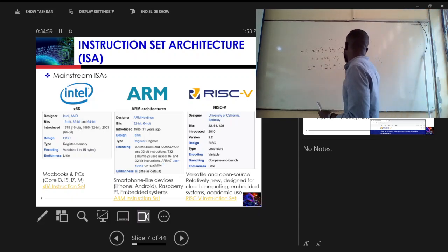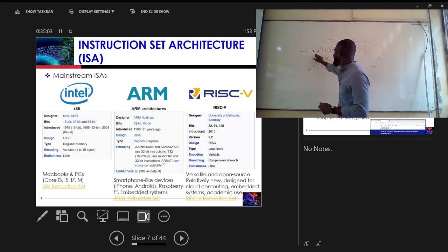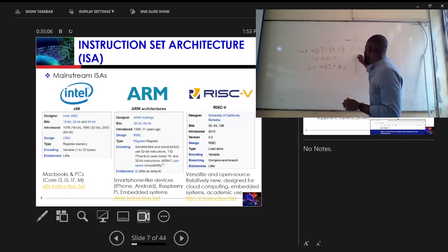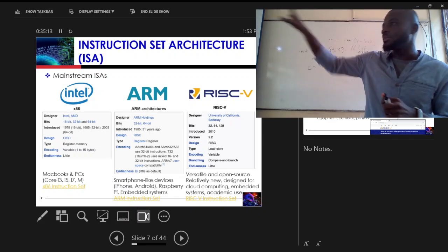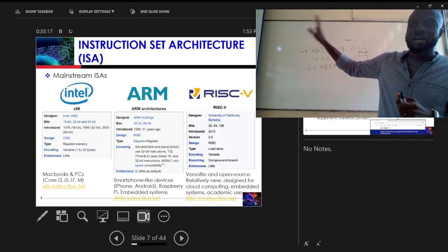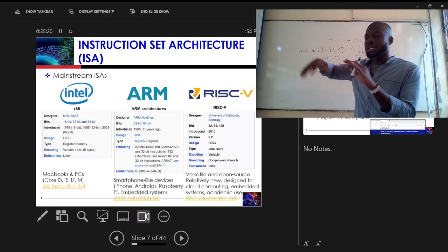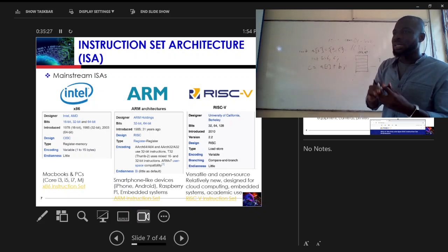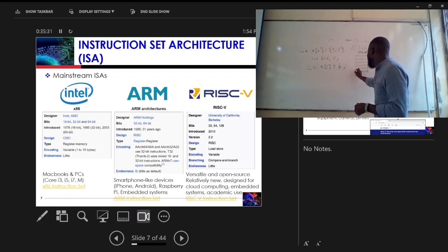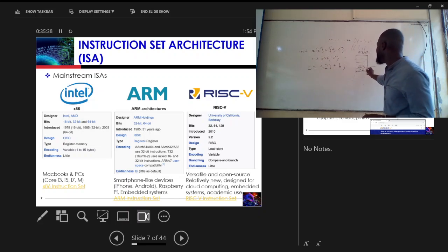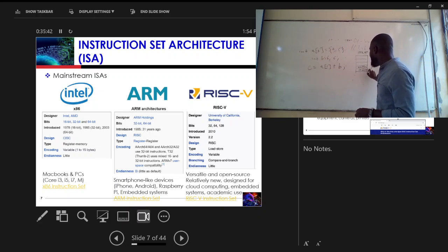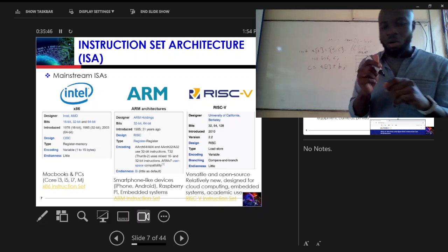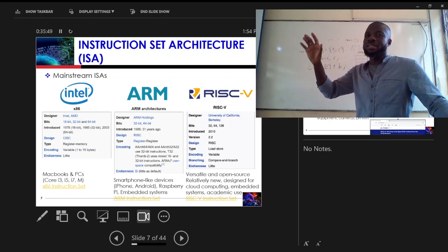What this line of code does in the actual hardware is create a memory space. You saw that within your CPU you have two memories, the ALU, and the register file. Anytime you declare memory in your C code or high-level language, it will create space within the data memory, not the register file. It will create space for storing A1 and A2. The values of A1 and A2, one is 4 and one is 5, so it stores 4 here and 5 here. Now, when you declare variables within your C code, what does it do?